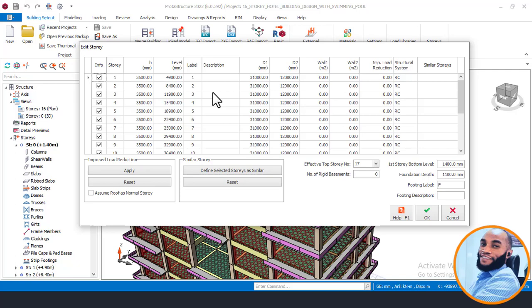Now, in that case, you will see that the imposed load, or the live load percentage, for the lobby or the walkway compared to that of the classroom hall will be different. Different in the sense that the load at that particular time is concentrated in one particular place, which is the classroom, while the walkway, the lobbies and the restroom might have just one or two persons, maybe someone who is coming to the classroom or who is outside not feeling fine, I don't know. But the concept is that